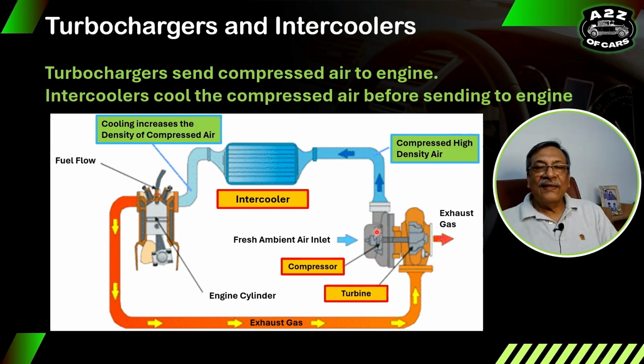And again, like I said in the beginning, when you compress anything, it gets hot, right? So if it gets hot, the density goes down. So if I need to increase the density, I have to cool it down. That is where the intercooler comes into play.